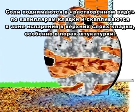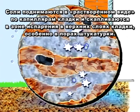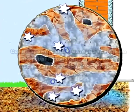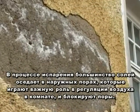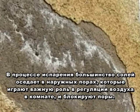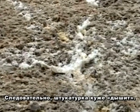The salts rise in a dissolved in water condition into the capillaries of masonry and are deposited in the evaporation zone in higher layers of masonry, especially in the pores of the plaster. The salts of building materials are also dissolved by the moisture stream, rise and additionally enter the pores of the plaster. Due to such evaporation, most salts are deposited in air pores, which are crucial for the regulation of the atmosphere in the room and clog the pores. The breathability of the plaster is thus reduced.